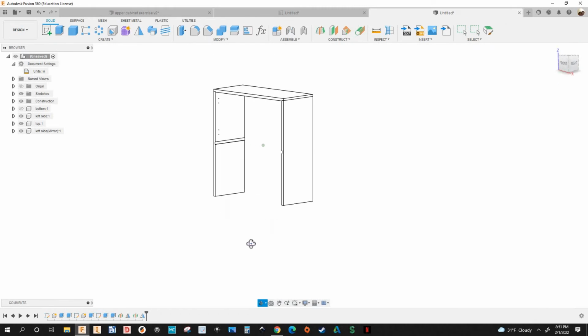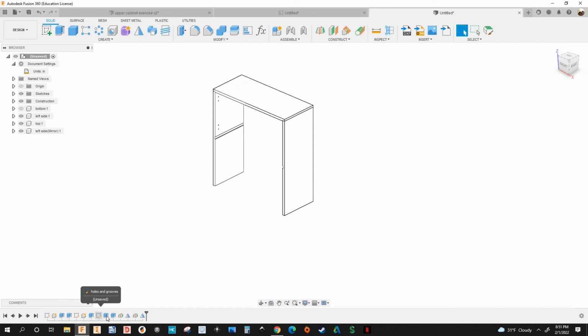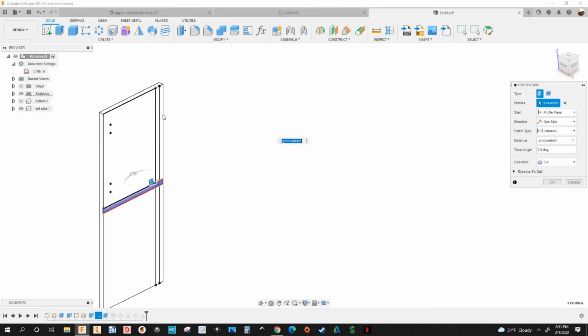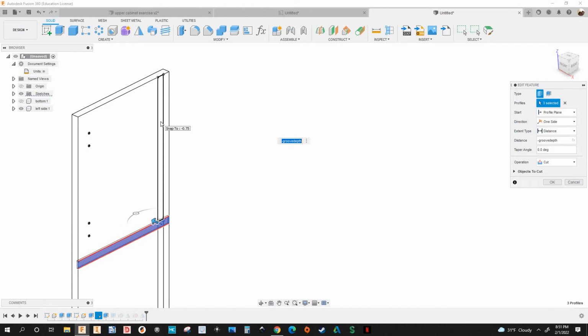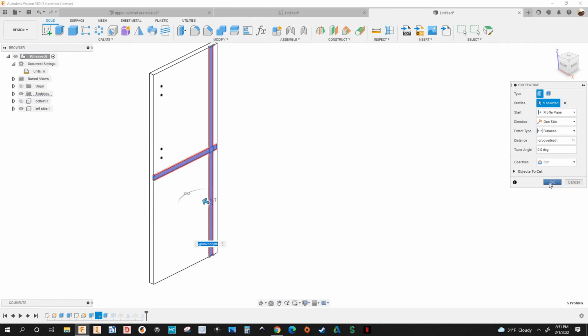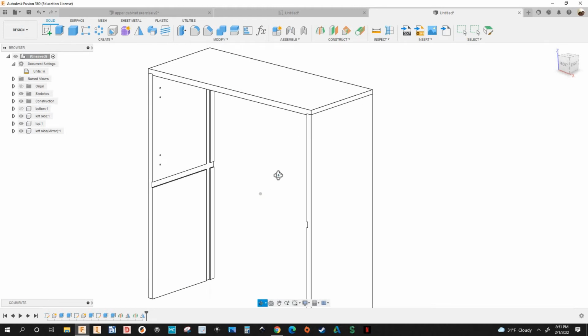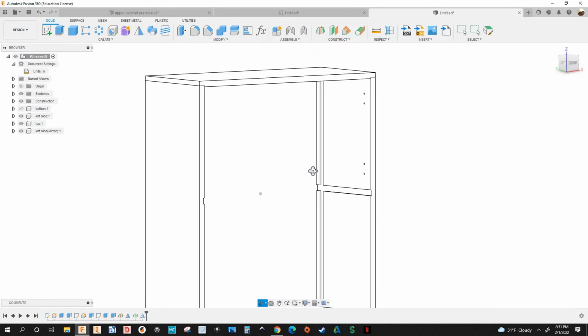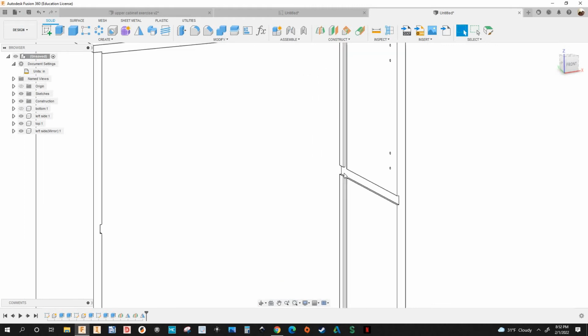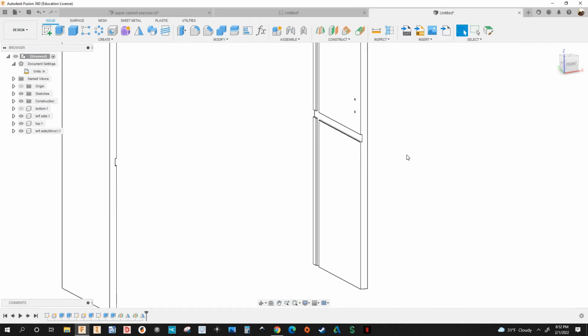Okay, and select that extrude feature right here, holes and grooves. Right click, edit feature, and I'll select that profile there, and this one right here. I'm gonna click OK. Okay. But I don't want this groove to come out there. I don't want to see that in the back. So let's fix this right now.